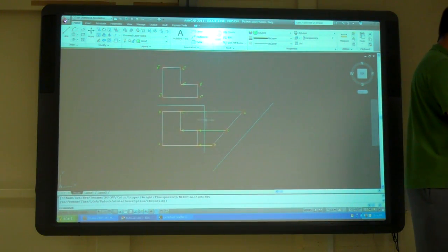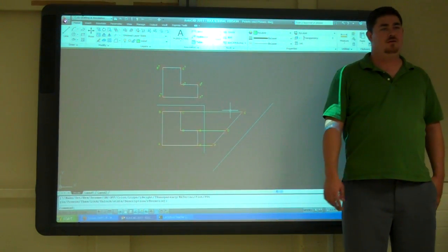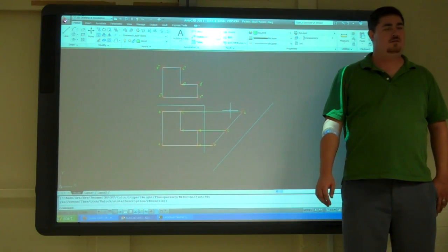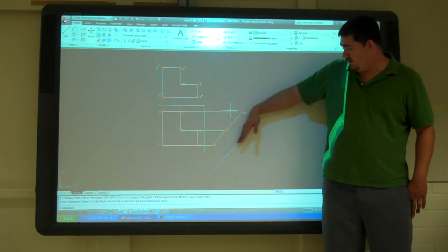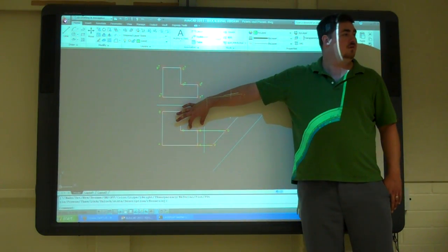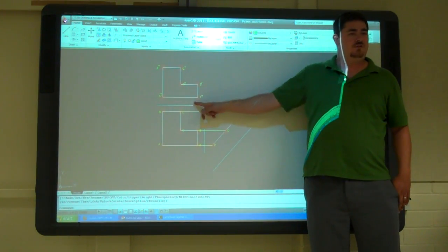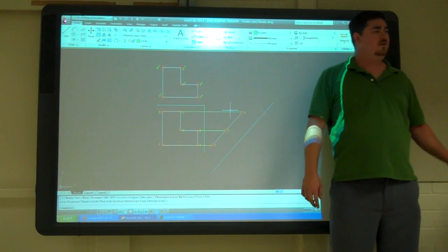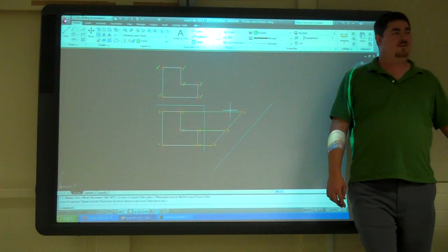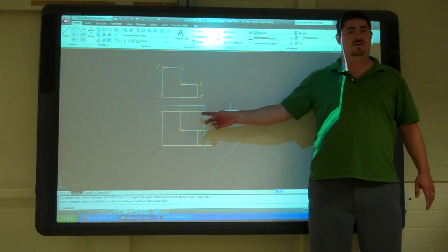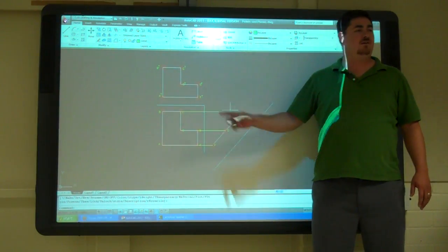Okay. Alright, so why did I connect those points? Because that's where I want to measure, right? So you know where to make your line. I'm going to measure 2 views back. So this is 1 view, 2 views. So I need to measure from this folding line back to the points. And so I drew the line. Why draw the line? Keep tracking. Once you change your UCS, I can't use tracking anymore to do that.